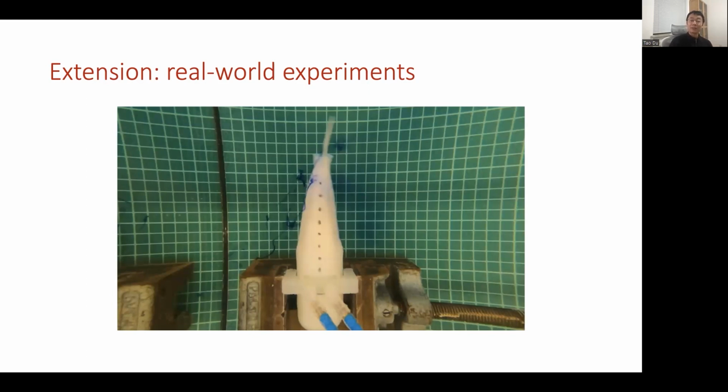And in this work, they actually leveraged the HydroNet simulator to do some very classical robotic tasks. I believe they did system identification to build a virtual model for this fish, and they also tried to optimize the control frequency, basically how frequently you swing the tail of the soft fish, so that you can maximize the thrust by interacting with water.